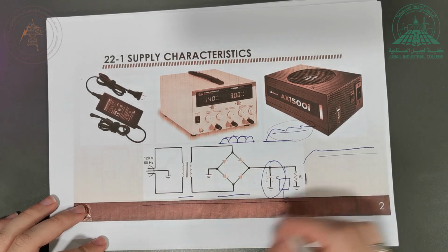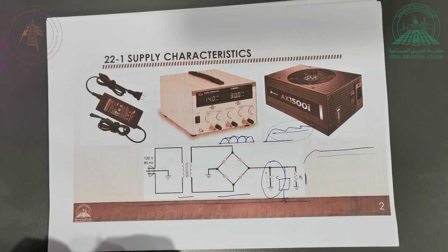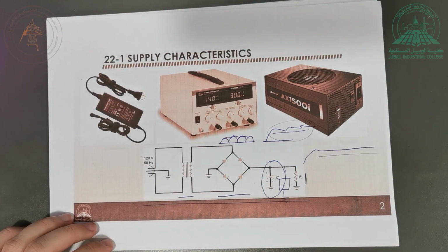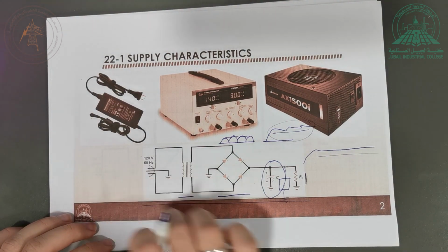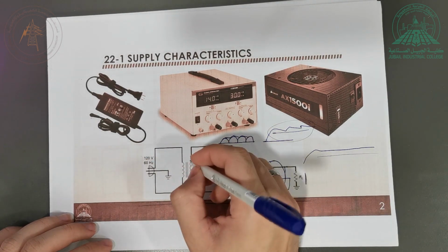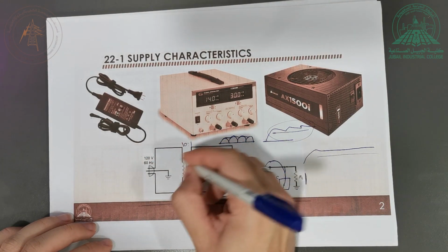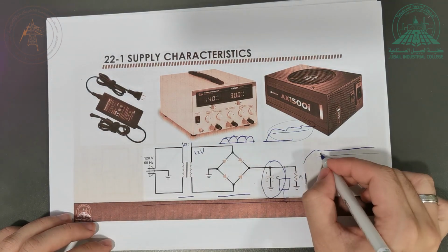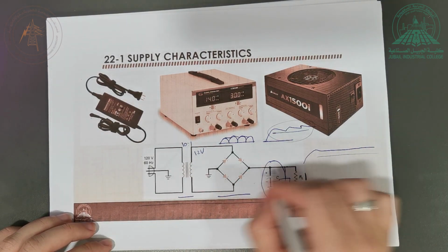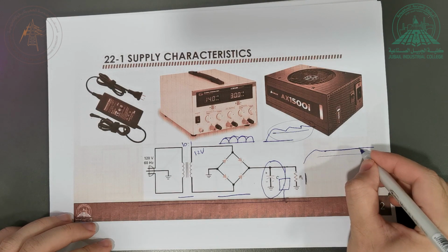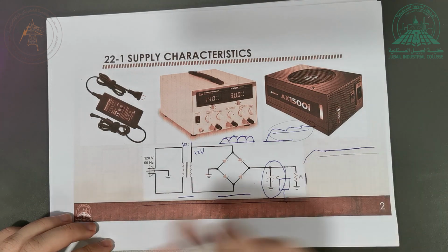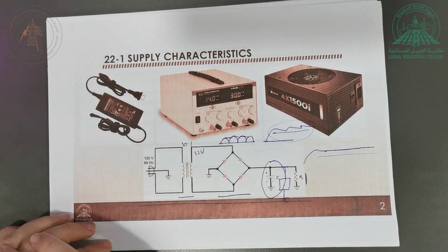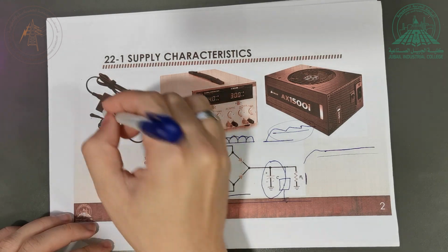So this whole thing is a regulated AC to DC converter, right? This is what you see inside the charger here, right? It will step down the voltage from 120. For example, if the ratio here is 10 to 1, the voltage here is going to be 12 volts. And then after the other processes that take place here, the output voltage should be a constant voltage like that, at 11 or 10 volts or whatever, depending on the settings or the parameters that you put here. So this is like the power charger.